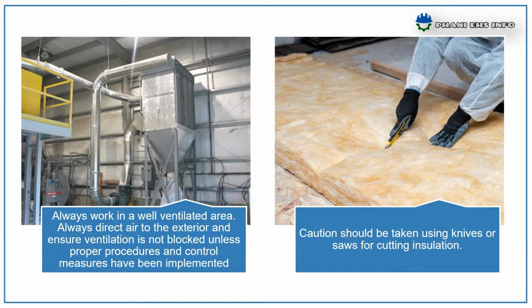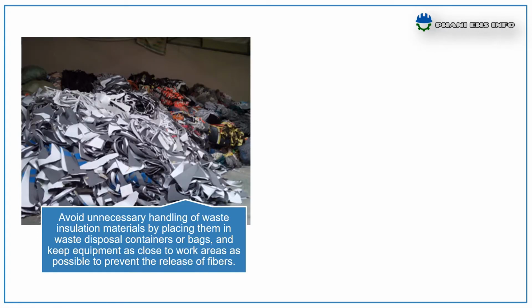Caution should be taken while using knives or saws for cutting insulation materials. Avoid unnecessary handling of waste insulation materials by placing them in waste disposal containers or bags, and keep equipment as close to the work areas as possible to prevent the release of fibers.